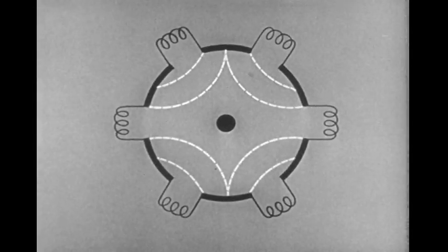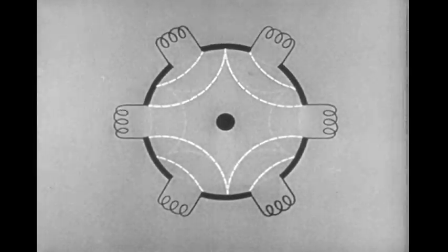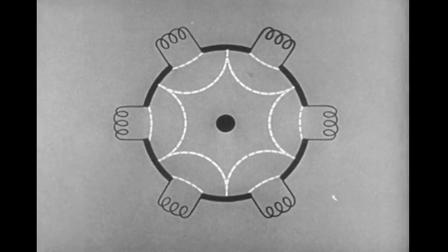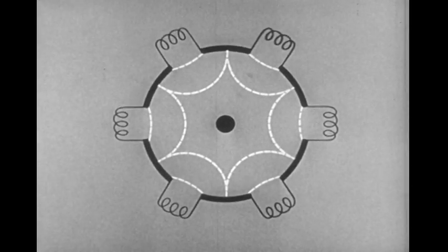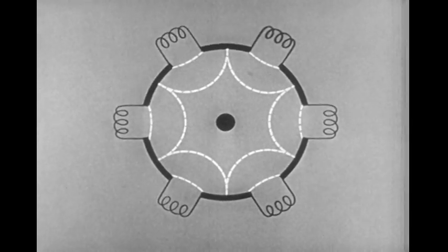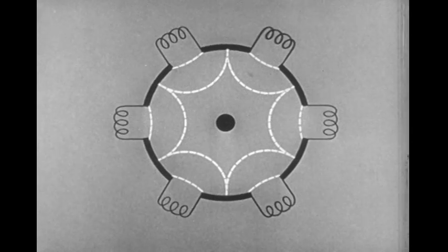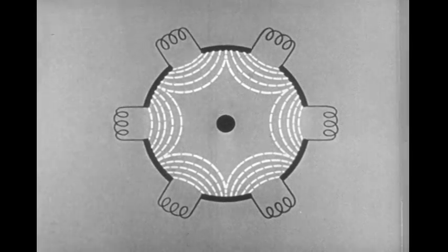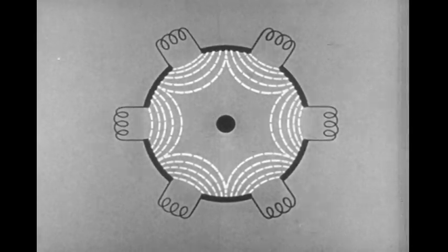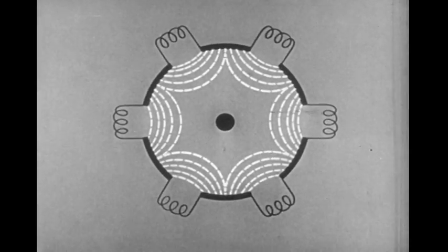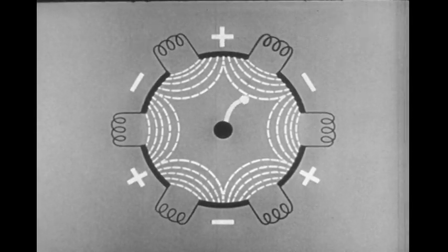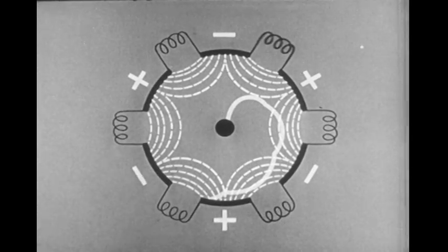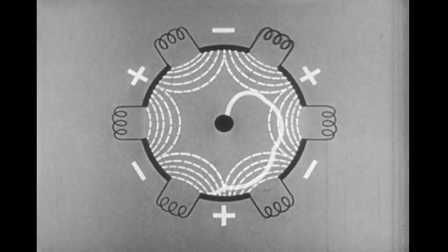This is another frequency with its resultant field. And this is the most efficient frequency with its resultant field. It is this frequency at which the tube is designed to operate. It will do so if the proper magnetic force and the correct DC potential are applied. With the magnetron oscillating at this frequency, electrons leaving the cathode are governed by the same forces as those in the plane magnetron. The electrons leaving the cathode will move in the usual cycloids, passing 2 segments per cycle of the oscillator until they finally reach the anode.